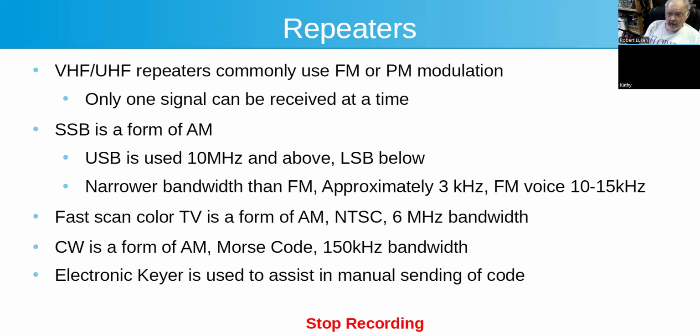So there's no carrier and there's no opposite sideband. Whereas in typical AM, you'll have a carrier, and on each side of it is the sideband, which is your voice modulation just shifted up in frequency. And it has a mirror image on the lower side.